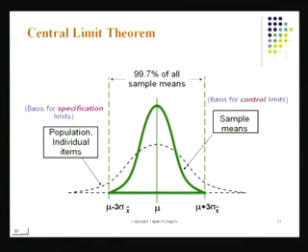That's the reason for constructing a subgroup of some size. A subgroup is basically a sample. I have individual data points, and what I really do is collect a few of these data points and look at their average. That's how I calculate my x bar value. And that's something we'll be doing again as we go into our example.